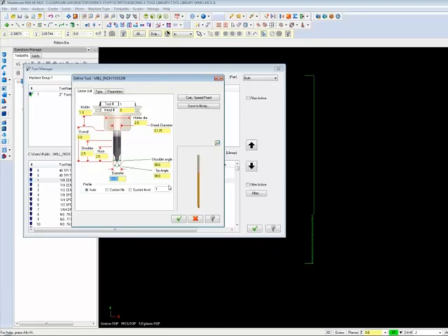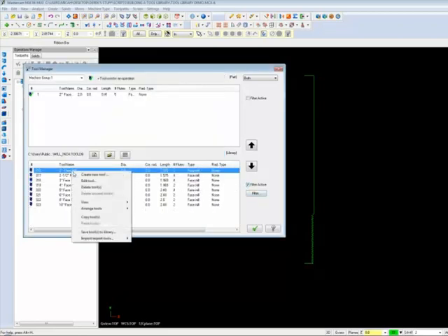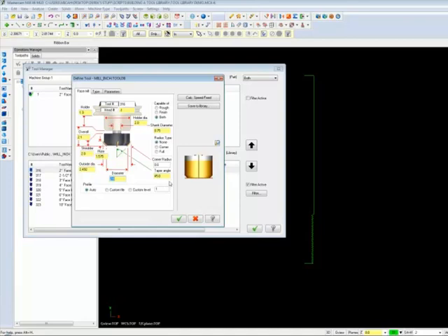Okay, well, let's back up a second and cover Mike's point real quick. So if we can go back into that shell mill, it's right there at the top. Just use the one at the top. Okay, so go ahead, Micah, let's get that back to 2 inch, 2 inch, so it's a square. And let's cover Mike's point. Mike, you wanted to have a corner radius on the insert? Well, yeah, normally they're never going to be sharp.